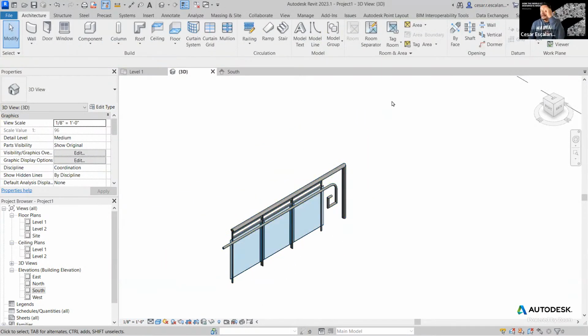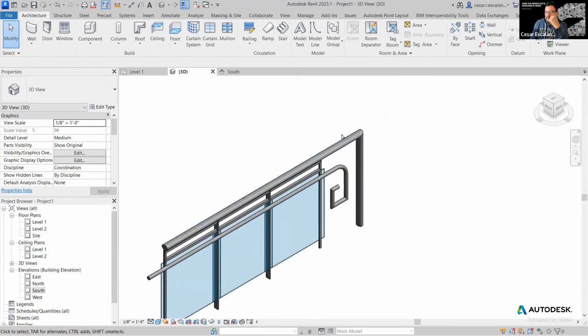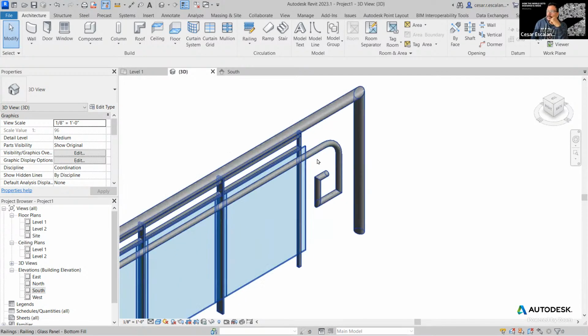All right, so let's make a railing from scratch. I just shared some tips on how to edit the handrails without accessing the post. One of the drawbacks of doing this manually, maybe is fine for unique conditions, but if you're gonna have this typical condition everywhere, maybe it's better to build a post and then add the post and the balustrade distribution, because you don't wanna be doing this extension manually over and over repeated times.